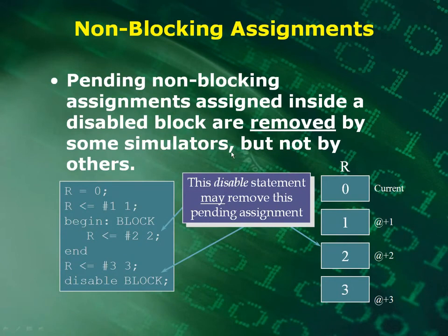Let's go back and look at non-blocking assignments a little bit now. Pending non-blocking assignments assigned inside a disabled block are removed by some simulators but not by others. So this is something I want to show you, and you could run across it.